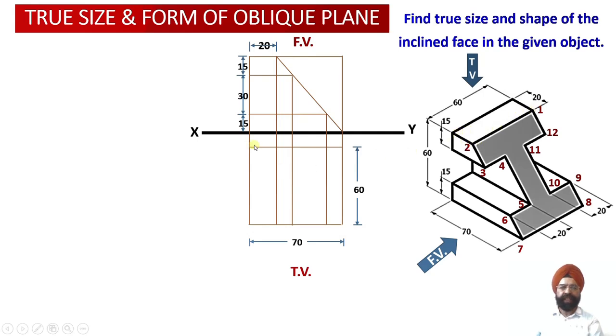So we can check, this is the rectangular surface which happens to be parallel to the horizontal plane, and this true shape has been obtained in the top view over here. Now after you obtain the true shape of this surface, I have to work out the projections of this particular surface in the top view. In order to obtain these projections, we are going to make use of the dimensions over here.